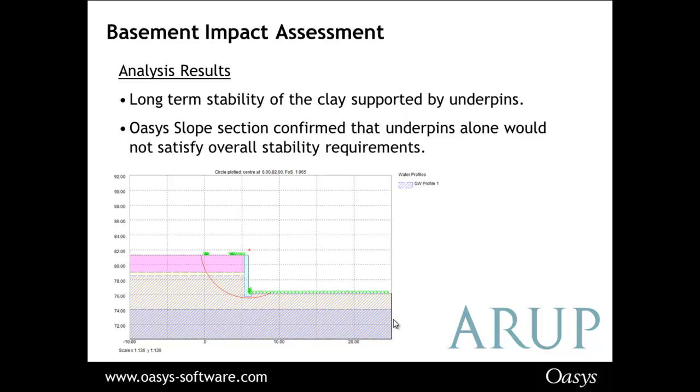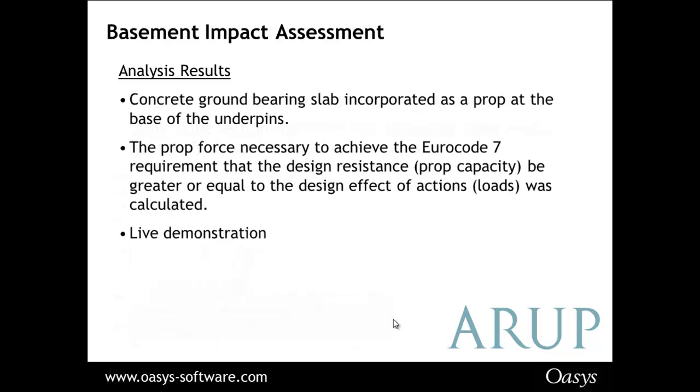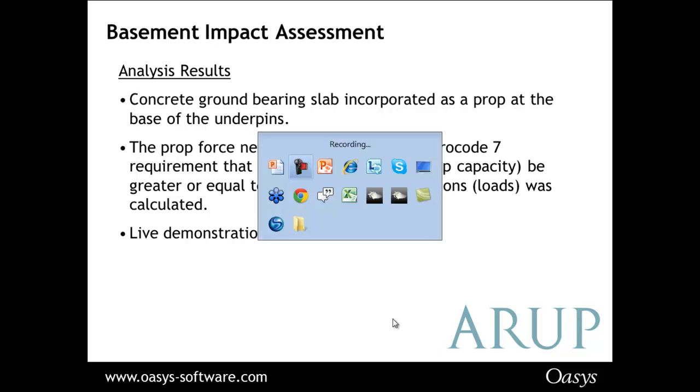So with all this, the Arup engineers ran a long-term stability analysis of the clay, which was supported by underpins. Oasys Slope analysis confirmed that the underpins alone would not satisfy the overall stability requirements. So for this particular analysis, the engineers carried out a Eurocode 7 factored analysis, and they stated that the concrete ground-bearing slab could be incorporated as a prop at the base of the underpins. So if I go into this analysis,